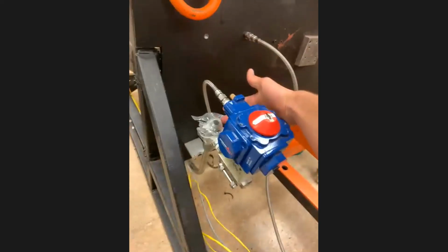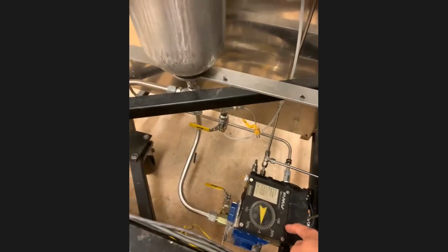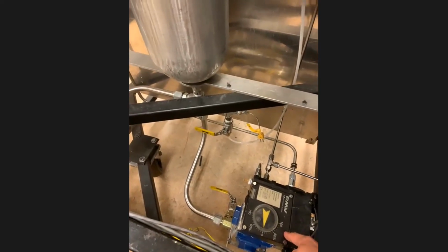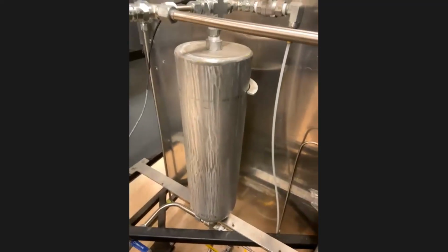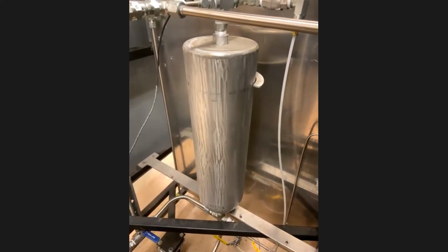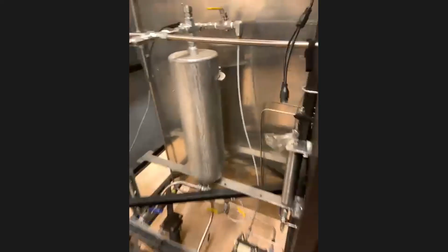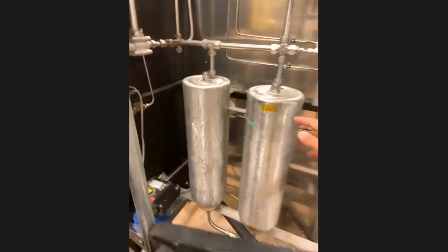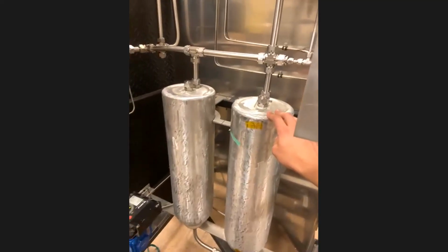And it gets its kerosene, or its fuel, from this hose right here, and the liquid oxygen from the other side. Hoses come back here, go through a valve so that we can control the amount of propellants that we want to flow. And that comes from a tank over here, which you may notice is just a scuba tank. And a similar thing on the liquid oxygen side, except over here we have 2 tanks because we need more liquid oxygen than we do kerosene.